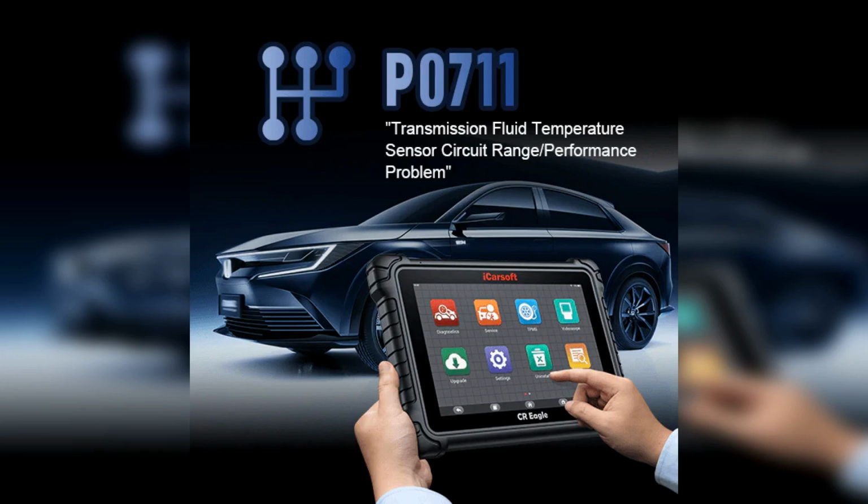of the transmission fluid. This is a thermistor with a negative temperature coefficient, where the internal resistance is inversely proportional to the transmission fluid temperature. In other words, signal voltage drops as temperature rises, and vice versa. If the PCM detects unsatisfactory performance of the transmission fluid temperature sensor, code P0711 is triggered.